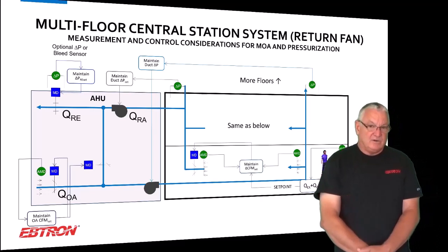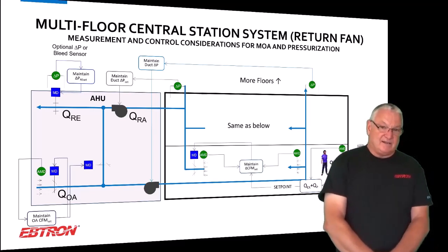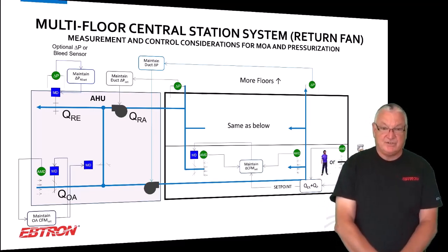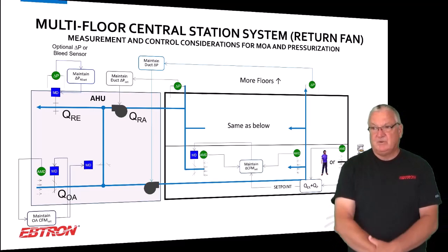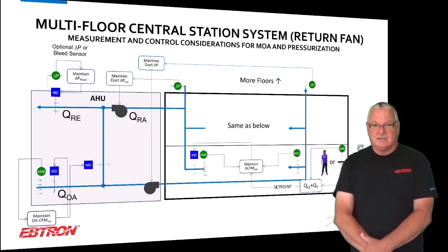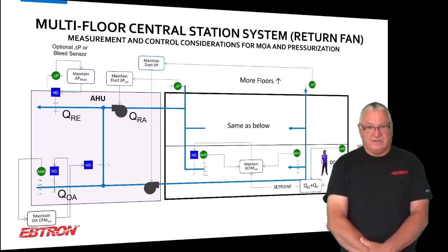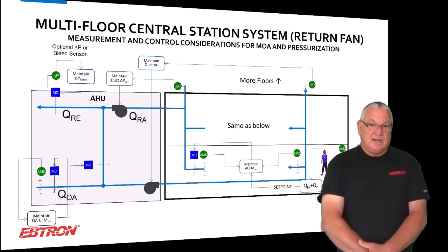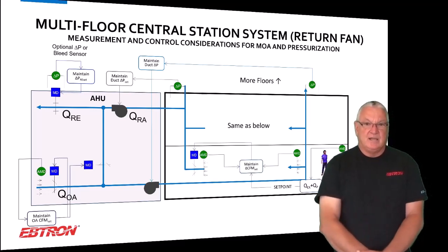The return flow, often depending on how the building's designed, there's no place to measure. If we get in early, we at least ask people to do some kind of stub ducting system. That works out pretty well. You use our AirIQ on those. It's a damper flow meter, just a stub duct for the return off the floor. And you maintain a differential.